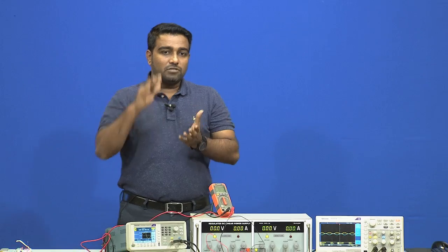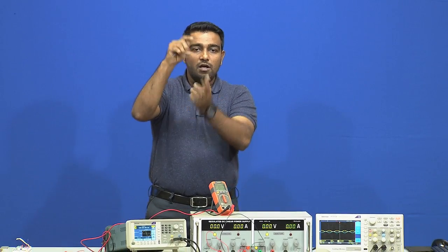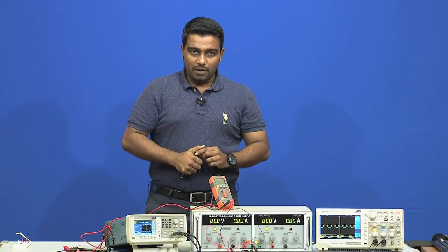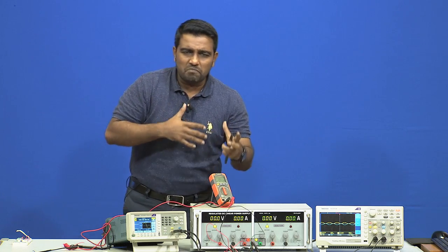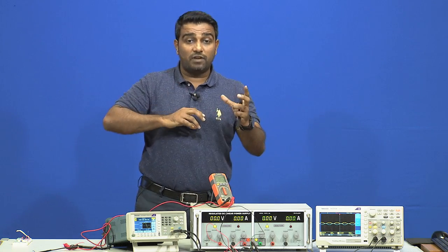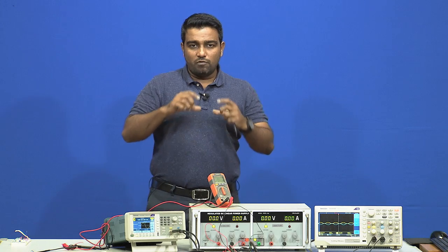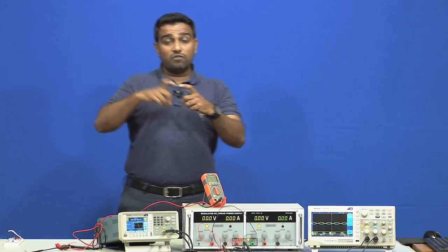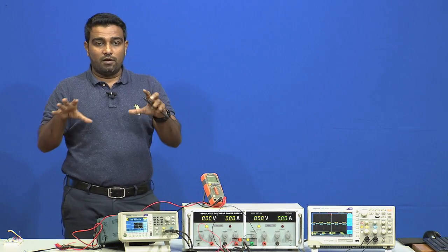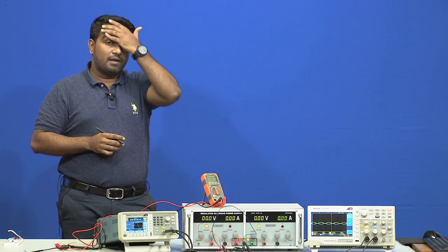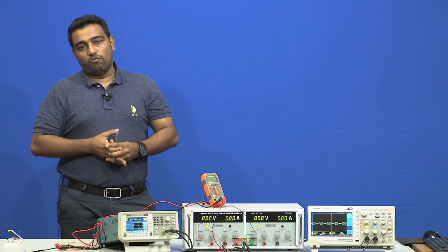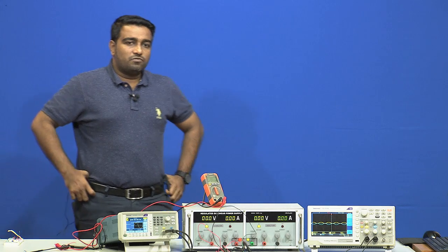No, it depends on how much supply you have given to the operational amplifier, all right. Here the maximum we can go is about 13.5 or close to 15. We will see that experiment also, what is the range in which the operational amplifier can work, alright. So, that does not mean that when we say infinite gain, we have infinite output voltage, alright. So, this is very easy.